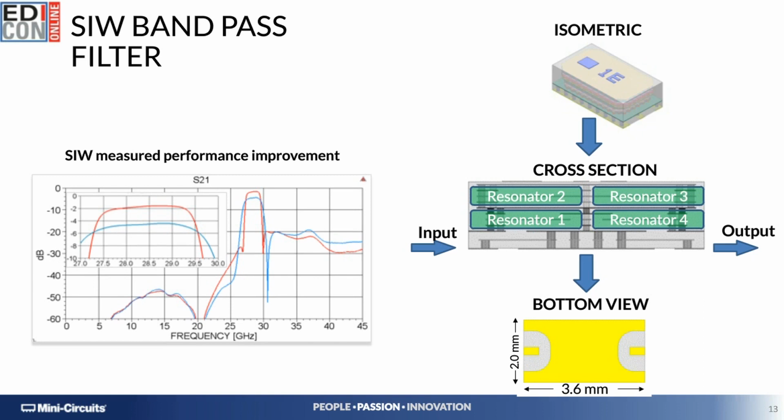We are developing as we speak, and we have actually implemented also on some of our developments, technological advances related to via implementations for these substrate integrated waveguides. We're employing also higher conductivity silver pastes and lower loss dielectric materials.